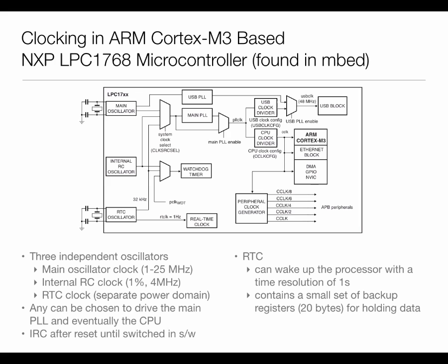It also has a provision for a real-time clock, which is separate out here. The nice thing about it is that it is used to drive a real-time clock, and it is battery backed up. So it sits on a separate power line, and you can shut down everything else, and this thing can stay alive. And these are usually very small, low in frequency. So this is 32 kilohertz.